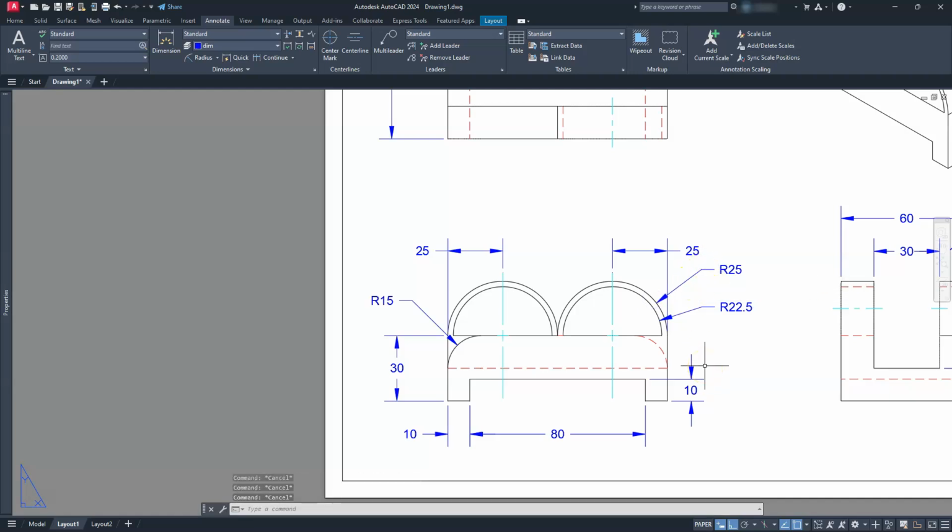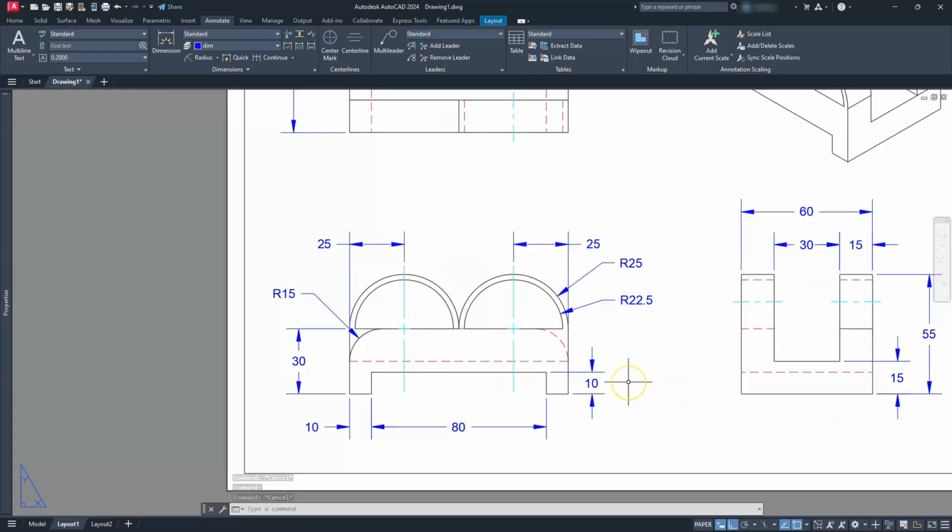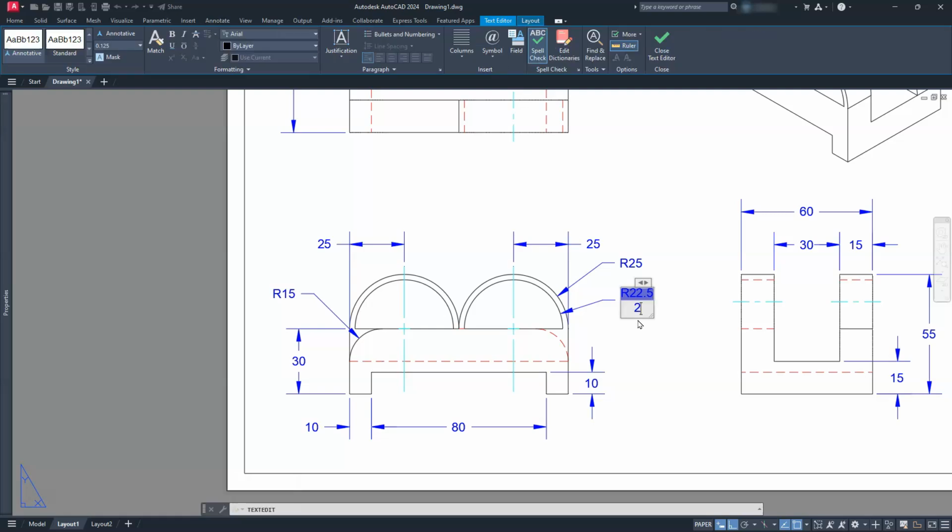All right. And then we can go ahead and modify these if you want. So I can select this one and do the exact same thing. And this one is actually a reference dimension as well. But you can go ahead and do that, and the easiest way of doing that is you just double click on the dimension. It should bring you up in the editing, and then you will go to the home button, or hit the end button and then hit enter. And then I can type in my 2 places. So that's all that I'm doing on this part.